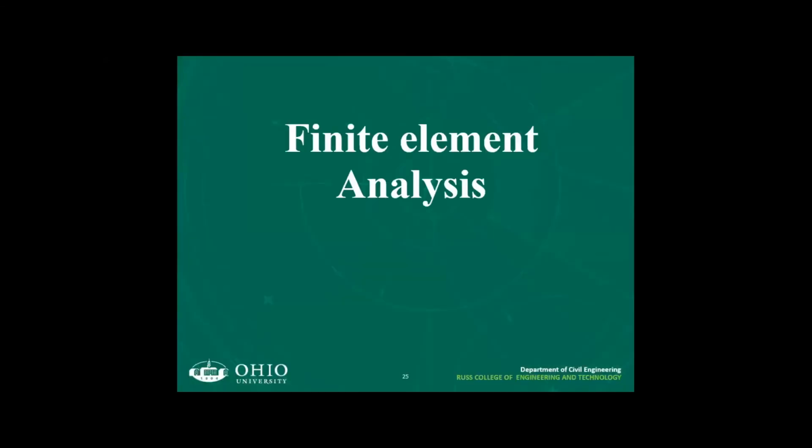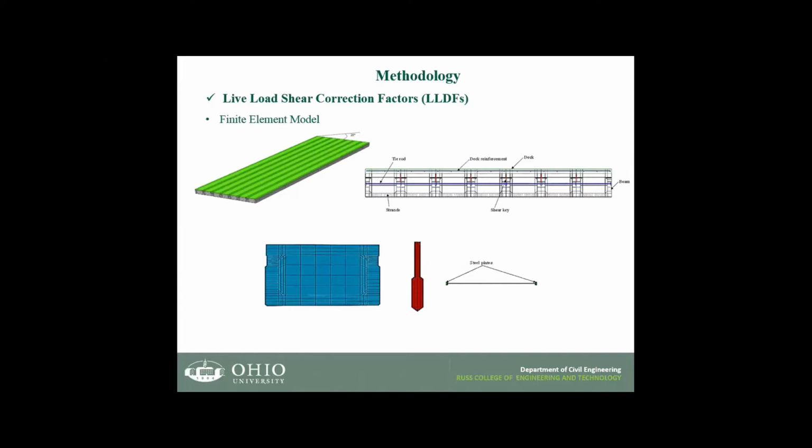The finite element analysis consists of modeling the deck using 8-node brick elements, and modeling the box beam, shear key, tie rod, and longitudinal reinforcement. The longitudinal reinforcement includes the prestress and the reinforcement in the deck. For the analysis, we used Abaqus because it provides linear and non-linear analysis, and also some flexibility for modeling different parts and connections. For the connection between the deck and the beam, full connection is assumed, so it works as a composite section.